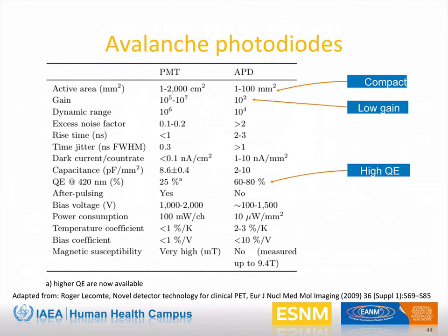In an APD, the signal generated by the incident light is internally amplified, typically by a factor of a few hundreds. Even though the signal of an APD is amplified by the multiplication process, it is not enough to be used without an external amplification in order to obtain a reasonable energy resolution, also thanks to the very high quantum efficiency.